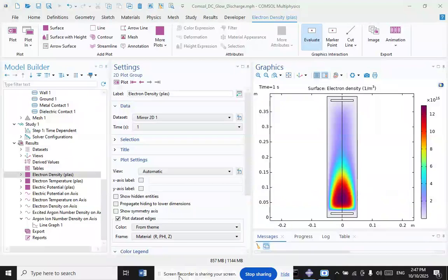The glow discharge starts as a normal glow. As the current is increased, more of the cathode surface is involved in the glow. When the current is increased above the level where the entire cathode surface is involved, the discharge is known as abnormal glow. If the current is increased still further, other factors come into play and an arc discharge begins.